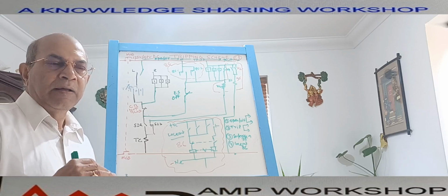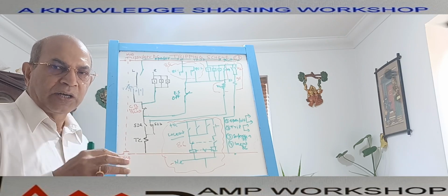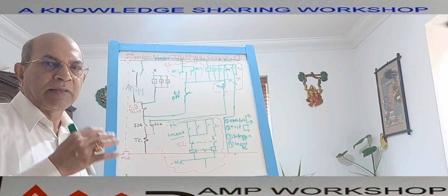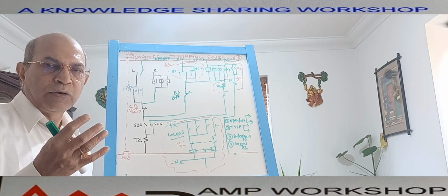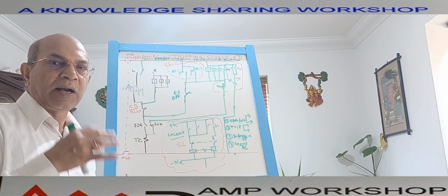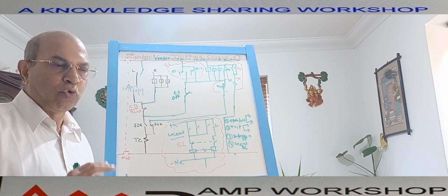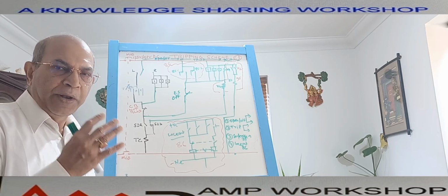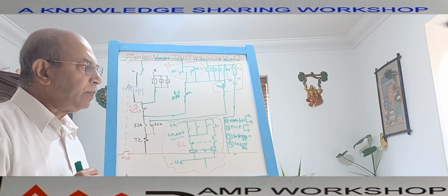The second is the opening of the breaker under abnormal conditions, either on the circuit itself or the remote end, any power equipment or other devices where the power is being supplied. If the breaker opens automatically, sensing that abnormal condition, then we call it a trip operation. So the opening operation of the circuit breaker we divide into two parts: the normal opening operation and the fault tripping operation.